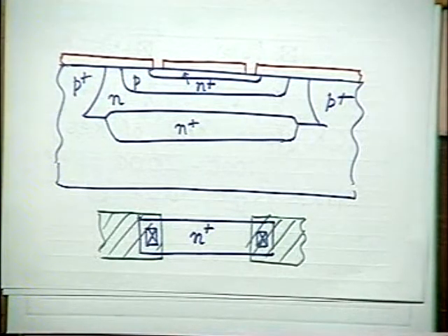Then can any one of you imagine what is the problem which I may face because of this? Any one of you? Please remember that this structure is otherwise the same as a bipolar junction transistor which I have fabricated in some other regions. Exactly the same. Only thing, I do not have proper contacts. Otherwise the structure inside has got all those layers, emitter layer, base layer, collector layer, buried layer, everything.